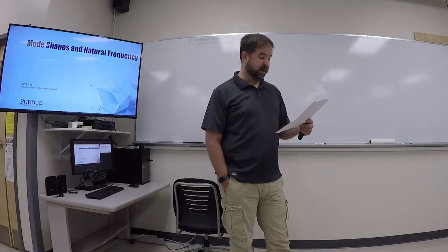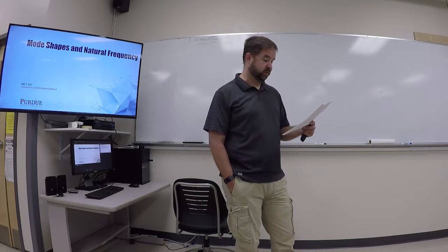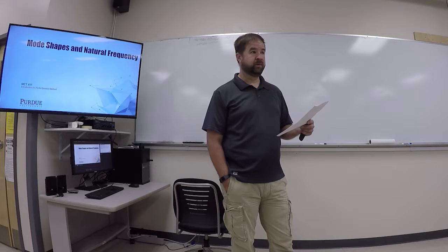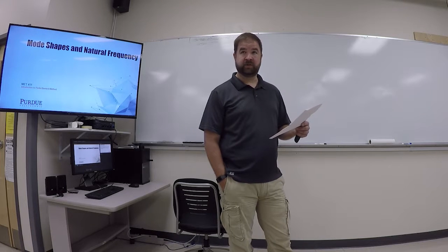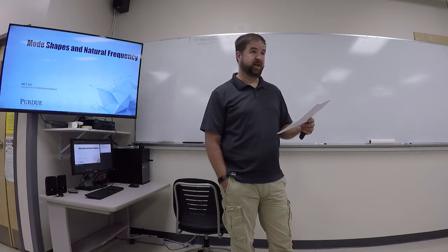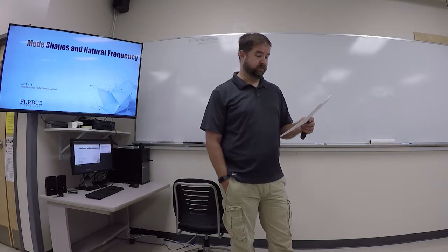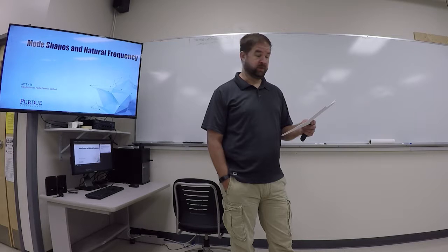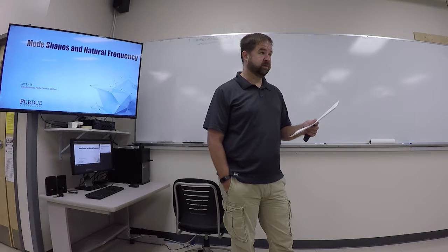And this one, you might have to get a little creative with your SolidWorks skills as far as making that shape. There's a couple different alternatives to doing that. You need to create a curved shell that is tapered in length. So making a curved shell that is constant width is easy. And there's a couple of different ways of doing this within SolidWorks.